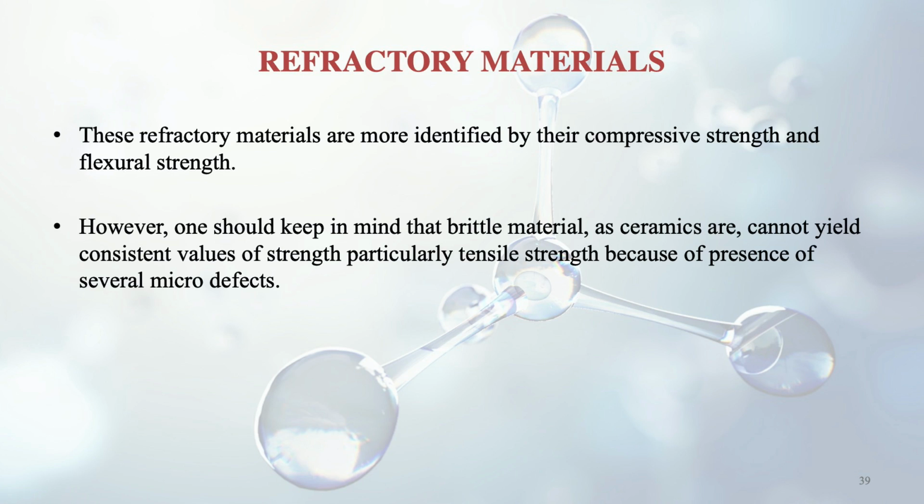Their tensile strength and ductility are not that good. They are brittle, but they have very good compressive strength and bending strength also, meaning their failure in bending does not happen every now and then. But we should keep in mind that these are brittle materials and they cannot yield consistent values of strength, particularly tensile strength. They don't give a fixed or exact value of tensile strength.